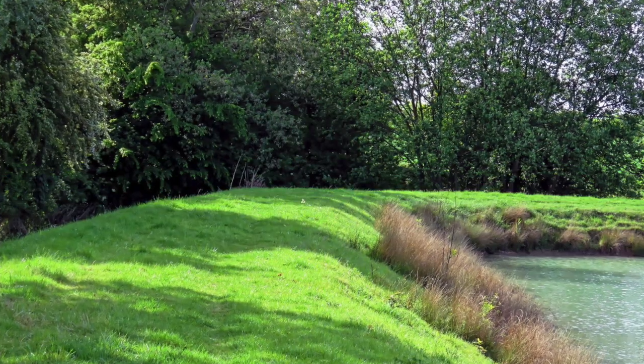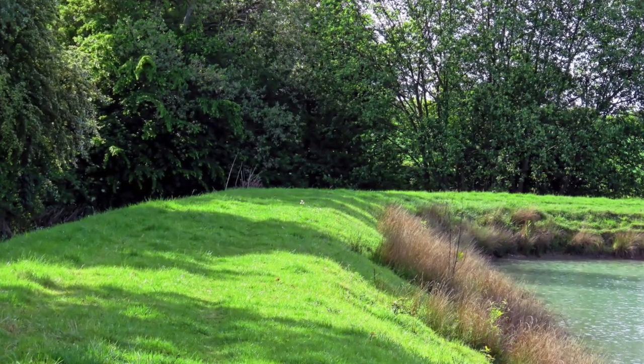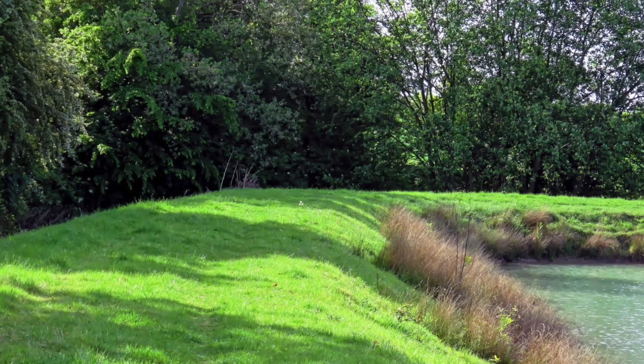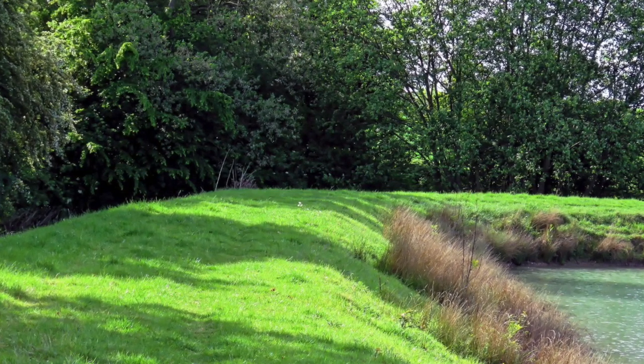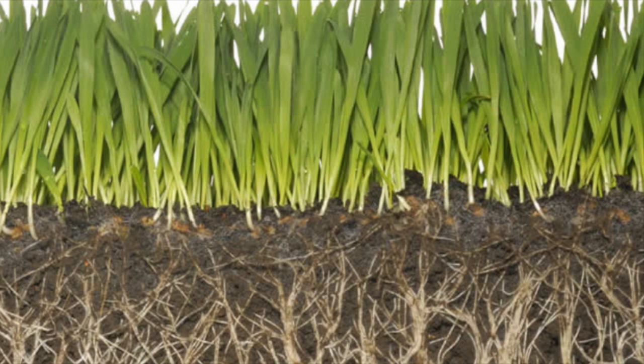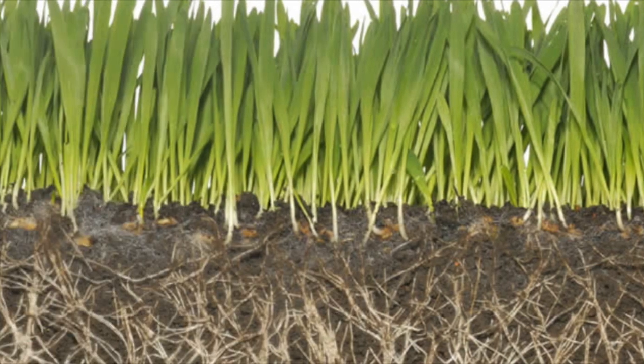After constructing, regular maintenance and inspections are required to ensure it remains in a good operating condition. Seepage from dam should be monitored on a regular basis. An increase in seepage may lead to piping failure.